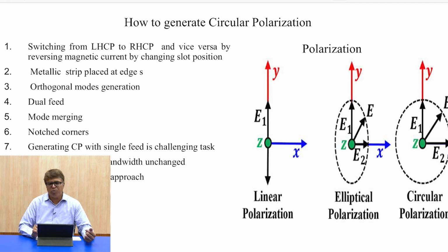As we have seen in the previous lecture, circular polarization can be achieved either by modifying the geometry of the dielectric resonator antenna or by modifying the feed, or the feeding technique, to the DRA. With both techniques we can achieve circular polarization, but the outcome of the field pattern of the E field will be like this.